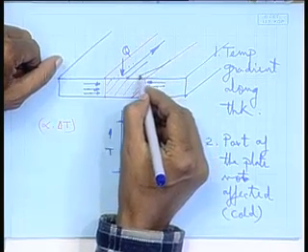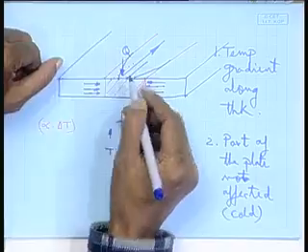Before that it will be somewhat like this, because there will be some transient level till I attain something like a steady state, right. Here the steady state is referred to as quasi steady state, meaning the same thing will keep on repeating over time, but actually at every point of time the temperature is changing at all points of the plate, but that changing pattern is continuing. That is what quasi steady state means.